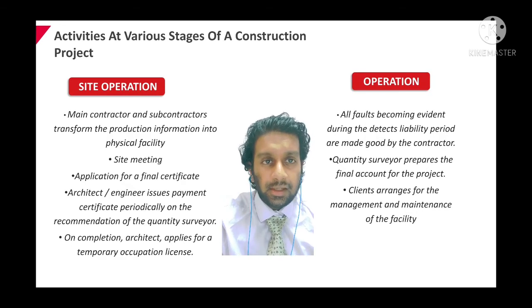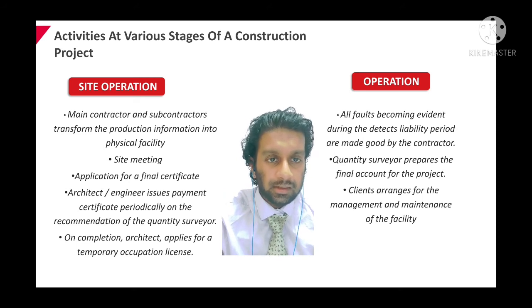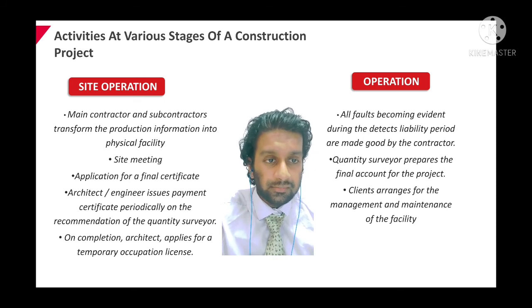And then we have site operation. This is where the main contractor or subcontractors transform the production information into a physical facility, with site meetings and application for a final certificate. The architects and engineers also issue payment certificates periodically on the recommendation of the quantity surveyor. On completion, the architect applies for a temporary occupation license.